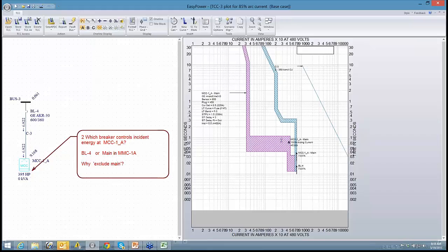So what I want to do is say, okay, what if I select this curve, hold down shift and select that curve, I can create a difference calculator, and now it shows me that at that current I have a separation of these two breakers of 155 milliseconds. Now that may be something we want to adjust or not, and as we do it we can see what the change is on the difference calculator. Okay.